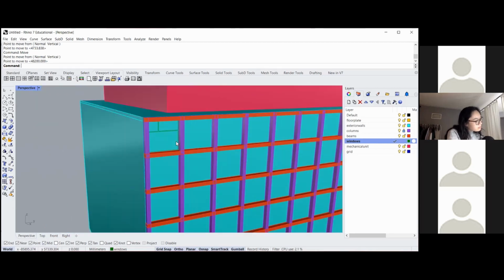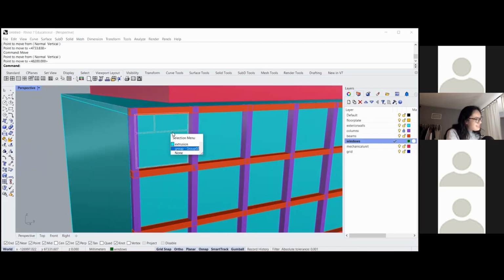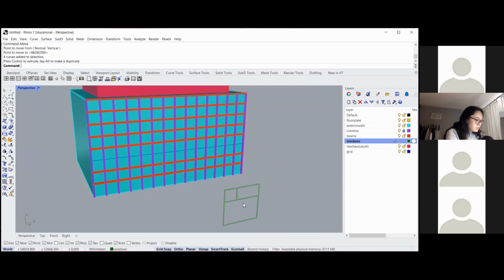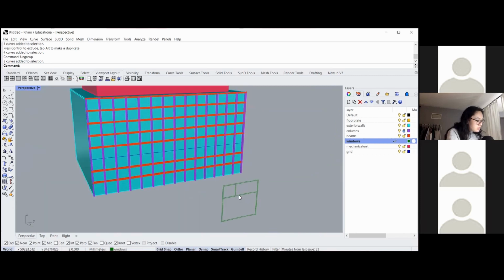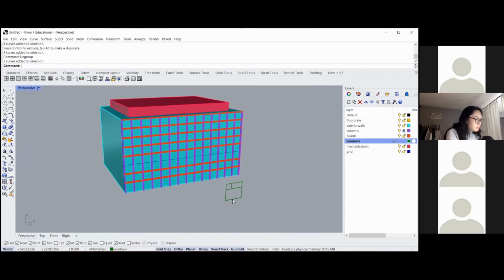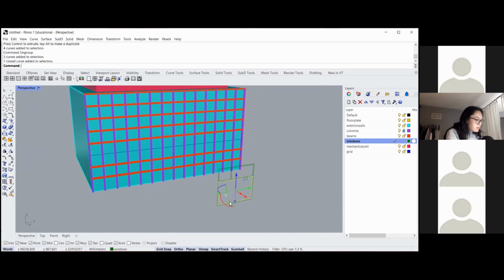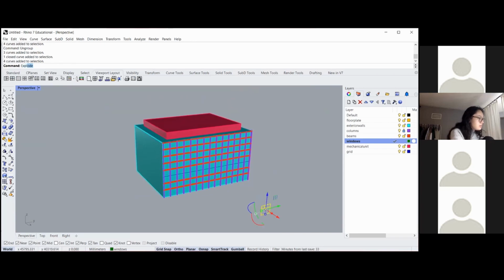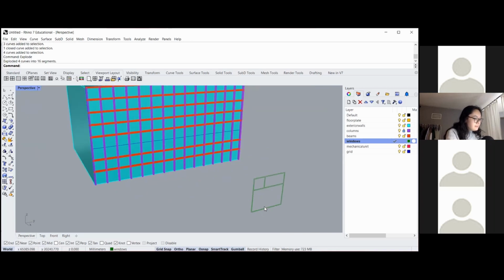It's kind of the wrong way. I wanted it to be the other way. Let's get that. I'm just going to flip this around. Go ungroup. Should I do this? Here's what I'll do. I'm going to extend things the other way. So I'm going to click. I'm going to explode these into their individual lines. And then I'm going to click this one at the bottom and I'm going to click extend.